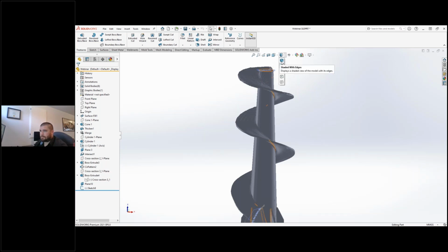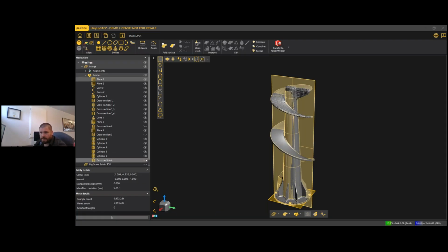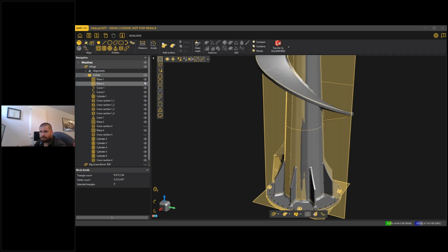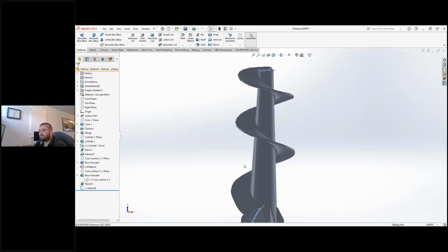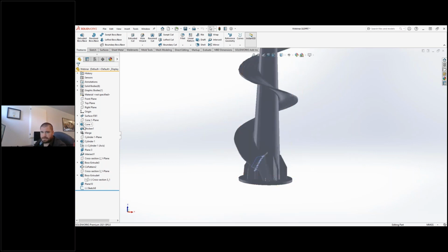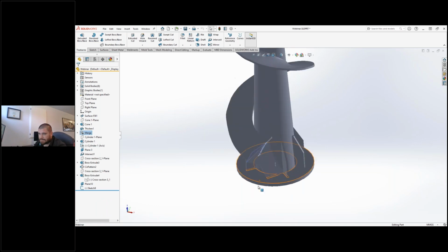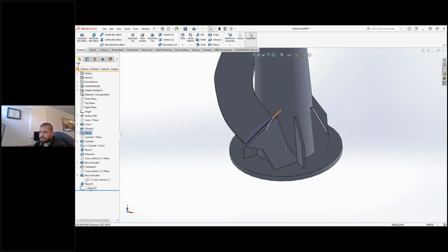I think you kind of answered that one already, but there's someone asking if you look at the sketches in SolidWorks, would they appear as fully defined or underdefined? Oh, so when I transfer a sketch? Yeah. So when you transfer a sketch, again, I might be repeating myself, but when you create a sketch, it really just creates splines of the cross section. So all these here are splines, and they will be fully constrained, yes, in the transfer here. Sorry, I'll just hide my mesh because it lags too much. It will be fully constrained, but only as an anchor, meaning there are no dimensions. It's really just an anchor in space.